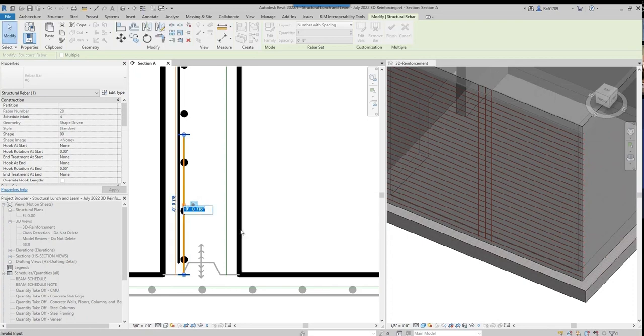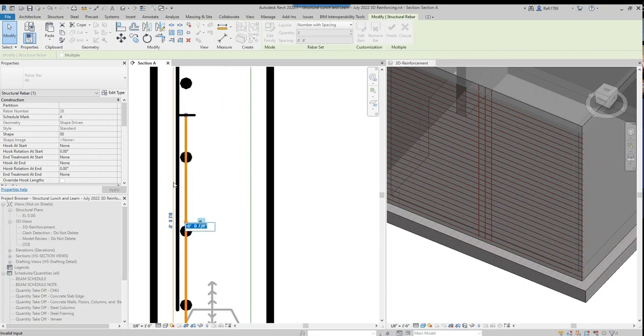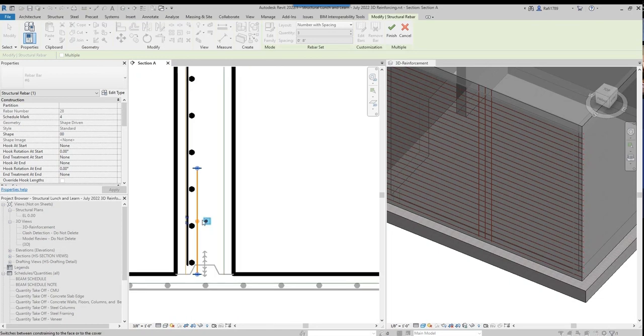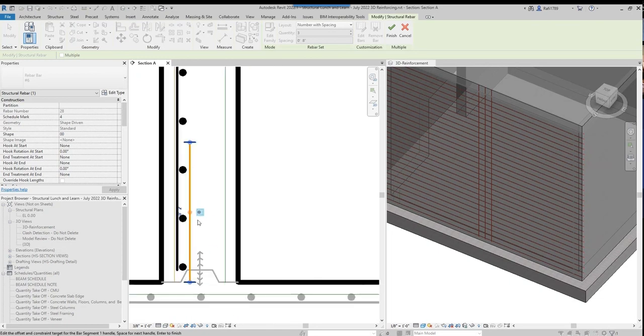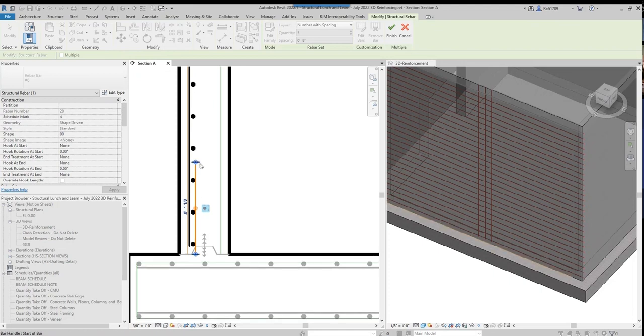Now, oh, sorry, that's not here nor there. So usually what we do is we space these bars about 1.5 inches apart. Now you have about a 7 1/8 of an inch, sometimes 2 inches. So you can place it about there. This is a 12-inch wall at a 3/8 scale. So I'm going to be a little bit more conservative because you'll see what I have to do here in a second.